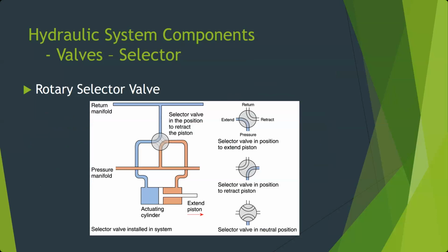so it'd be able to do that. And then because this is a closed center system, when we're not moving the valve one way or the other, it's going to have a neutral position down here where those passages are not aligned with any of the pressure return lines.